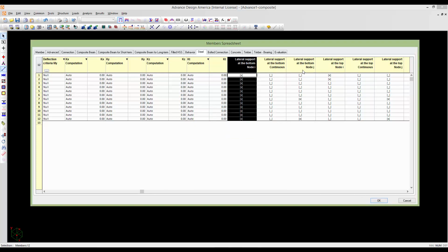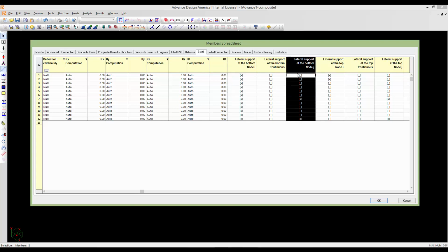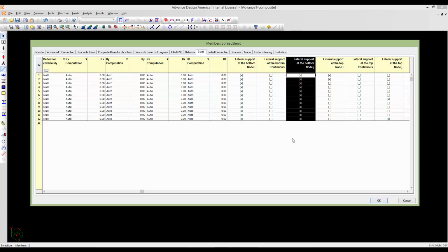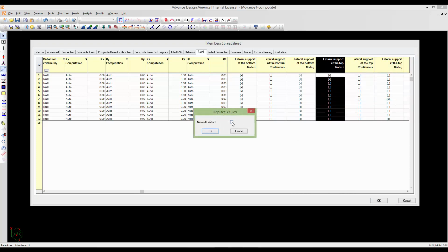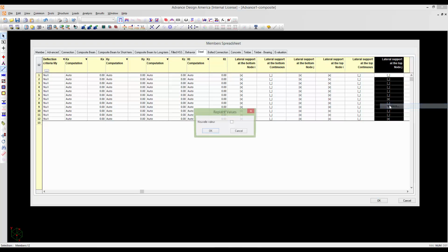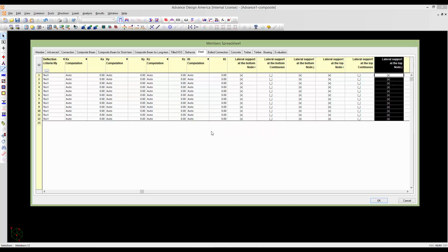at both ends. We will define lateral supports at each 8 meters, where we already have intermediate diaphragms. So also for node J, I assign lateral support for the top, yes, and also for the bottom. Pardon me, for the top at node J. Okay.